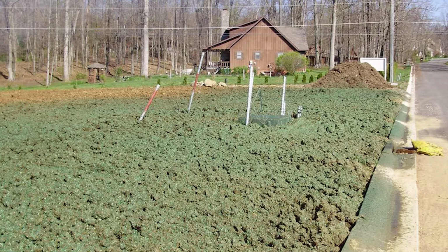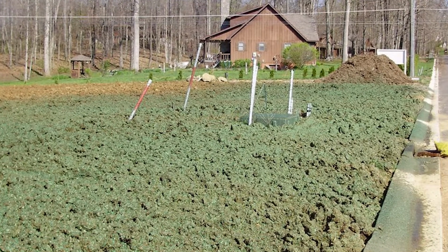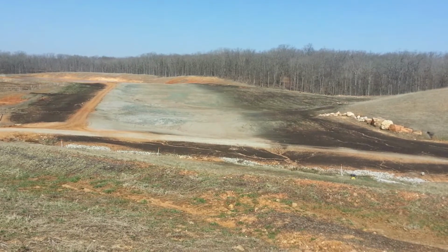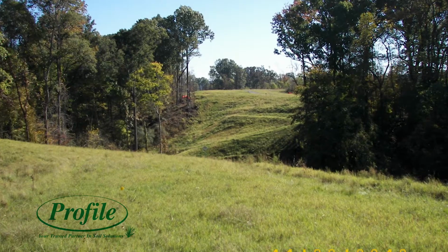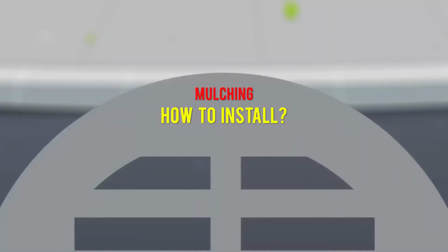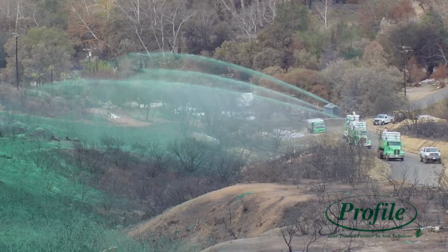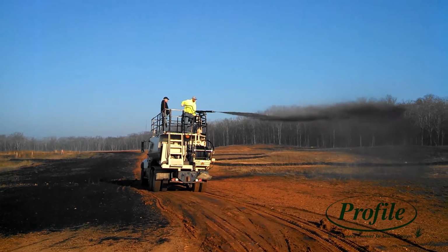How does it work? Prevents erosion by protecting the soil from wind and water impact, provides temporary surface stabilization, prevents soil from crusting, conserves soil moisture, moderates soil temperature, and promotes seed germination and seedling growth. How to install. Apply an anchor mulch as shown in the construction plans. Mulch should have a uniform density of at least 75% over the soil surface.